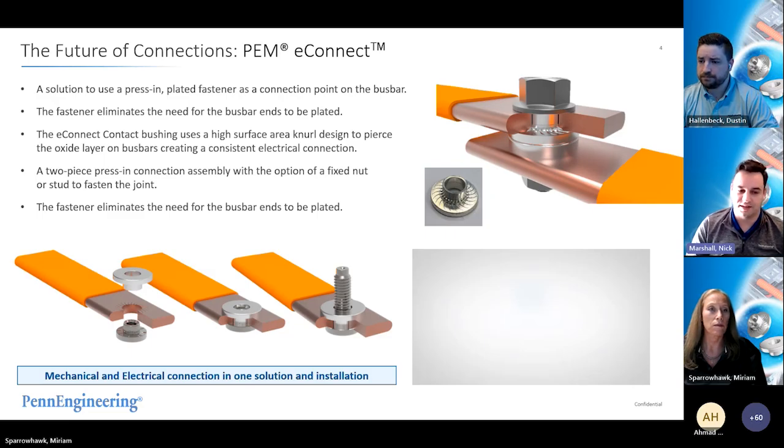And then our bushing is able to serve as the plated contact element on the ends of the bus bar. The reason that this is important is because if we don't use a component like this, the alternatives are plating the bus bars directly, which can be a very costly and inefficient process, or to use unplated bus bars in a joint where we're really trying to push the power through any oxidation layers or any inconsistencies on that surface. And to illustrate that, we've done quite a bit of testing to show this difference.